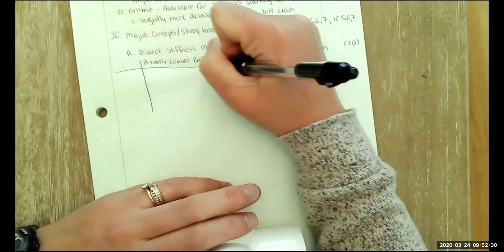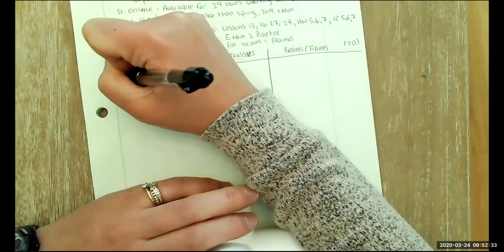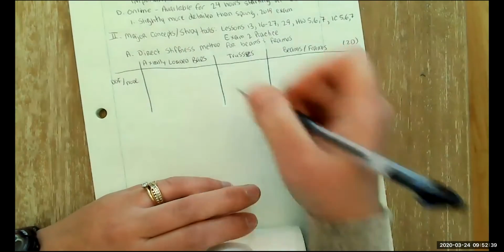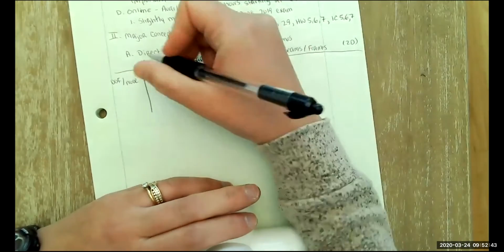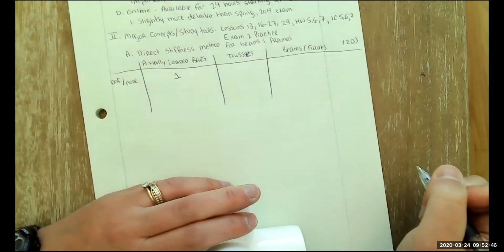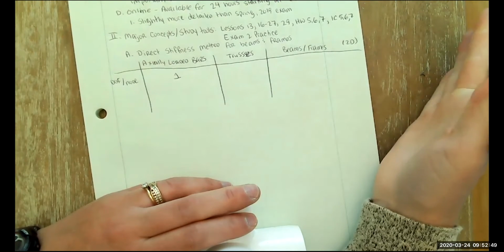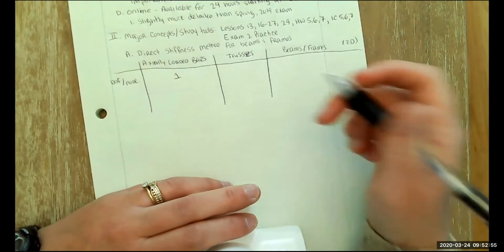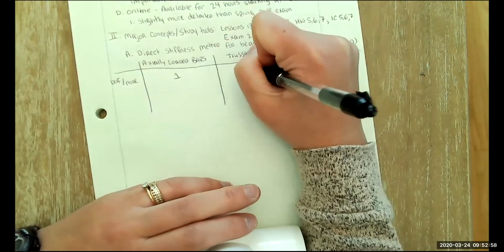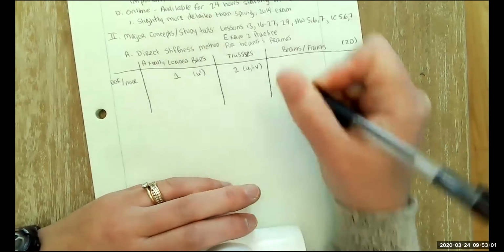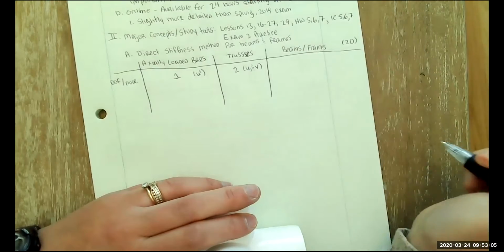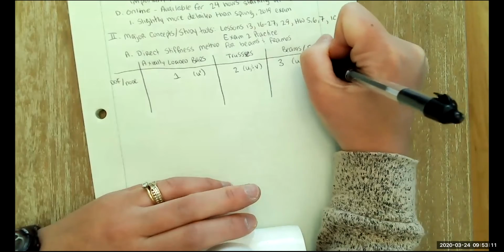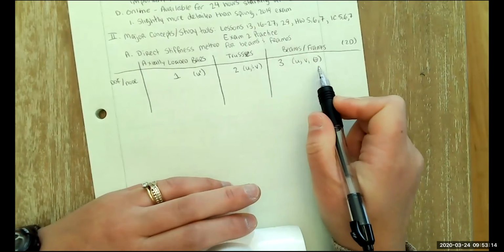And if I think about how many degrees of freedom per node, for an axially loaded bar, I'm only considering motion in one direction, so the X or the Y direction. So I only have 1 degree of freedom at each node. For trusses, since we're turning our bars at an angle, it's still axially loaded, but now we have 2 degrees of freedom. We could move in the U or the V direction. We have U and V. This would be the U prime direction, so in the direction of the bar. With beams and frames, we've added 1 more degree of freedom at each node. So we have U, V, as well as some rotation at that node, theta.